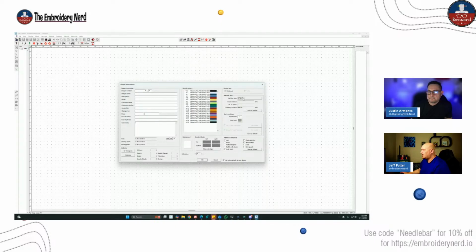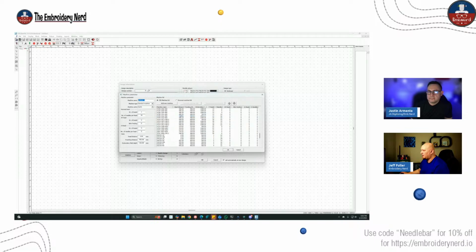Here I actually put in my machine. So I have the Sprint 8. If I click on that, there are different models of machines that I can put in here. Where the Basepac software gets a little bit different is if you have a machine that has special options and you put that in, then you can digitize for those special options. Particularly for this machine, if it was a multi-head, the traveling distance would be important because I can do head selection where the software will automatically turn off one head and turn on another head. I can do that, but I have to make sure that I have a machine that supports that. So if you're digitizing for head selection, you kind of need to know exactly what machine it goes on.